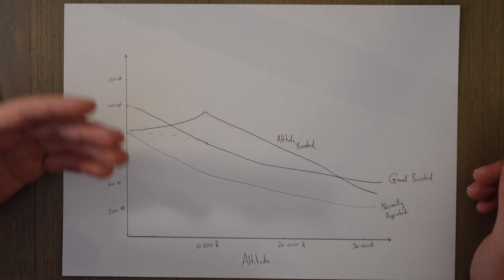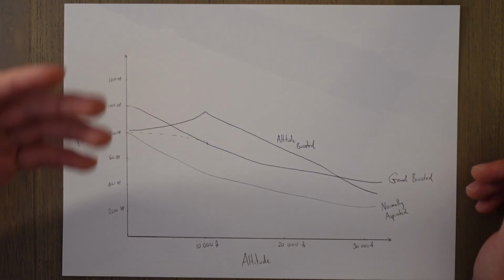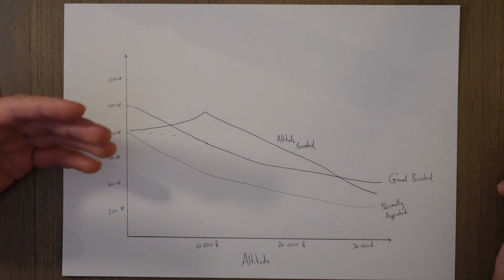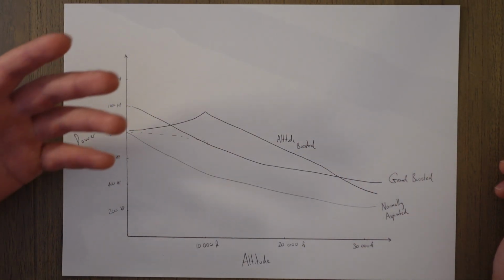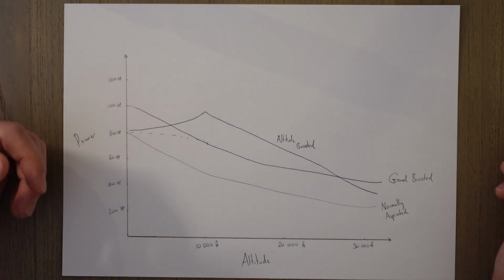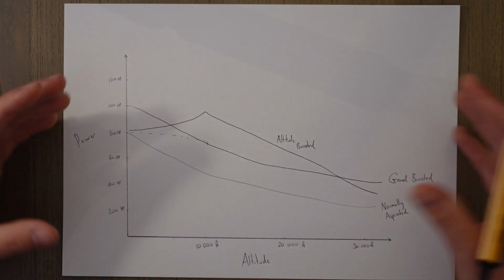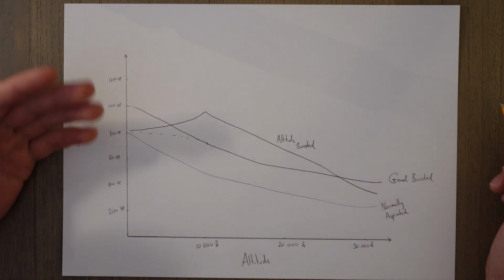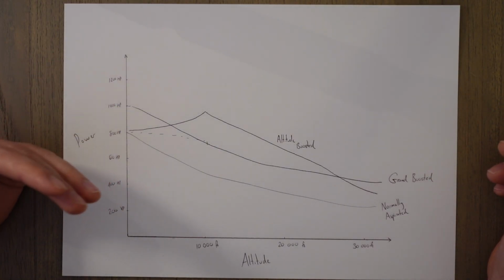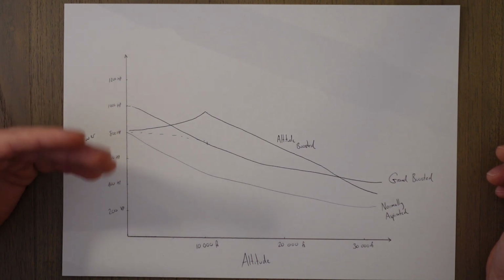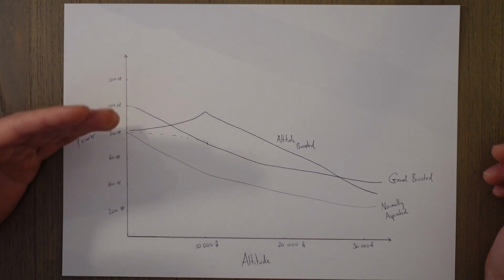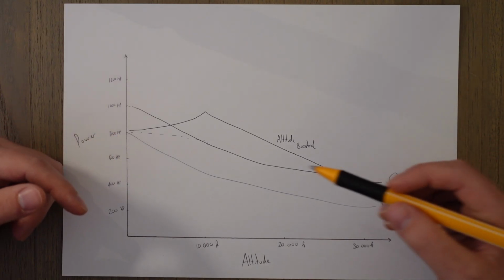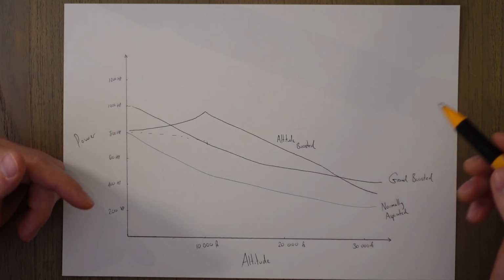With more pressure, it means there's more oxygen and there's more volume of air there as well. So that means that there's going to be a better combustion when that air and fuel mixture enters the engine. Another way to do the same thing is through something called a turbocharger. This uses the same impeller process to increase the pressure, volume and temperature, but instead of using gears from the engine, the turbocharger uses the exhaust gas from the engine to turn the impeller itself.